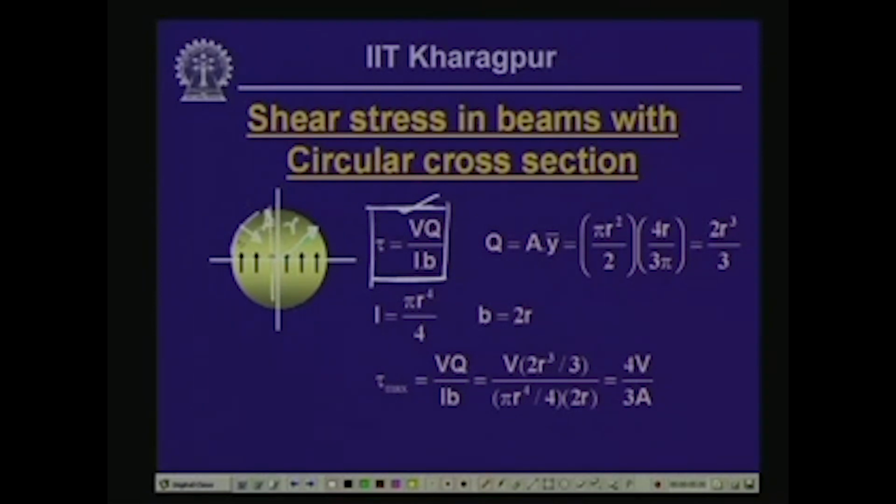So, the stresses we will have are all in the tangential direction, and hence these stresses are no longer going to be parallel to the y axis. So, it is very difficult to use this particular formula, or in fact this formula cannot be applied in evaluating the shear stresses in this particular zone.